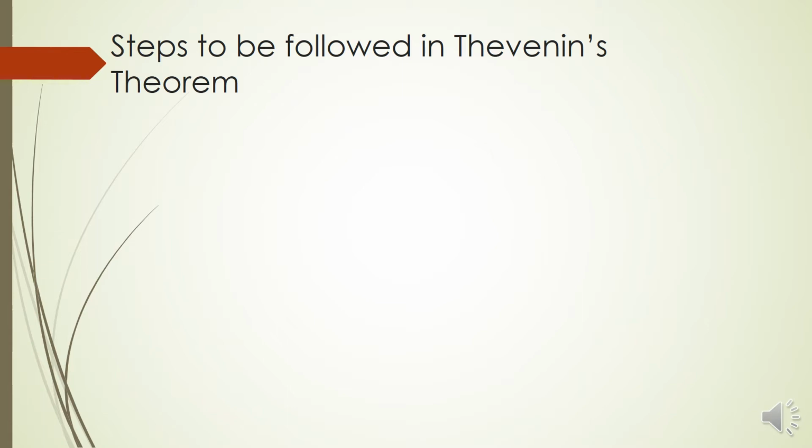So these are the steps to be followed in solving Thevenin's theorem. First step is to remove the load resistance RL.